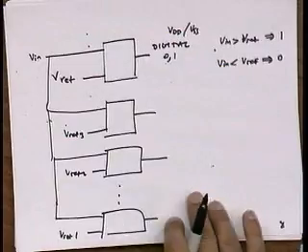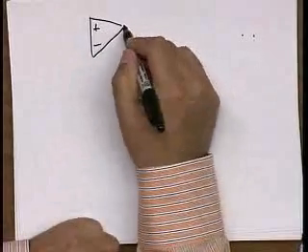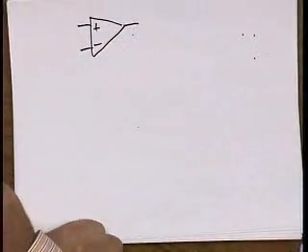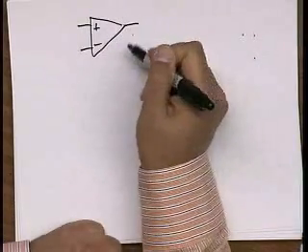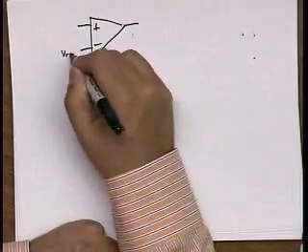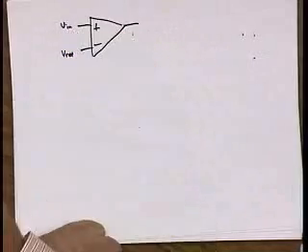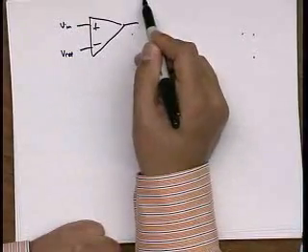You're right. But what I'm getting at is, why not just use an op-amp, right? A rail-to-rail op-amp. Right? So a rail-to-rail op-amp can swing all the way to VDD and all the way to ground, which is logic compatible. And let's say I put my reference here and my input signal here. Now if the input is larger than the reference, this thing rails, right?